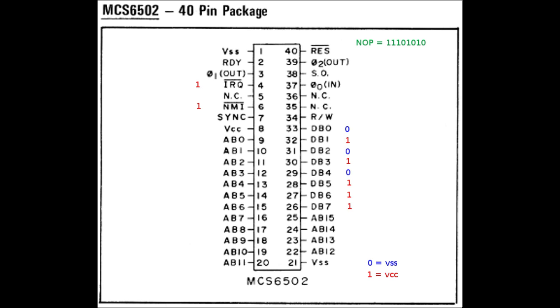But there are two possible problems. First, the CPU will write, so it will compete against the NOP generator. So we would need to use resistors again. And another problem is it would not cycle through all the address space because it could get enough interruptions before completing a whole address cycle from 0 to FFFF and back.